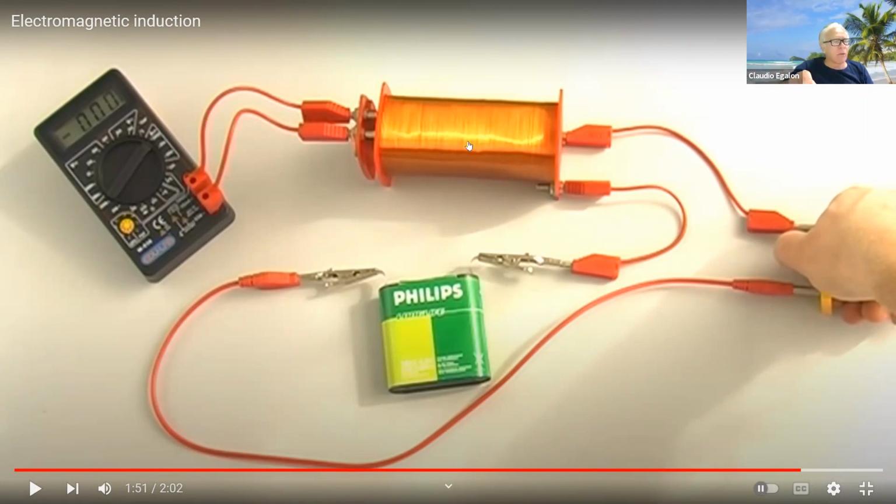However, the moment that you turn on, the current builds up from 0 to a given value in a very small amount of time. That's the transient, okay? As the current builds up from 0 to a given value, the magnetic field inside the solenoid also builds up from 0 to a given value. That's a changing magnetic field in time. Once the magnetic field reaches its value, there's no more induction. That's why this guy is going back to 0. Okay, here you go. Turning on and off the circuit.